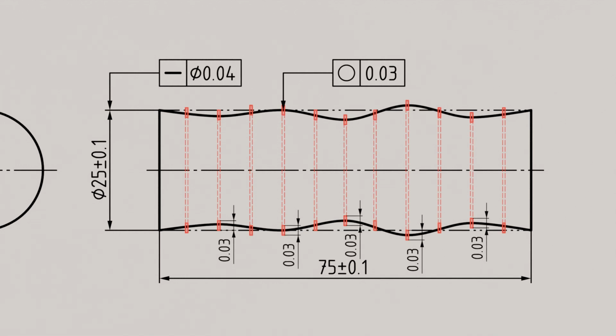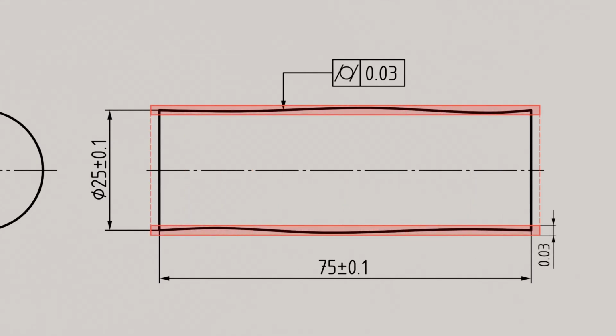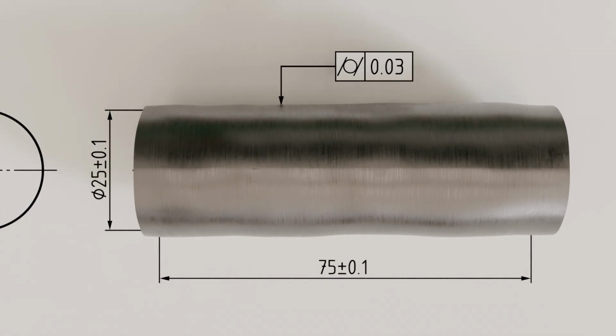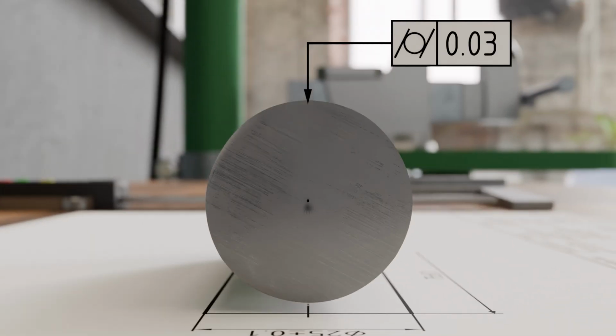For cylindrical parts, the deviation from the cylindrical form is limited by defining the tolerance zone not by two concentric circles, but by two coaxial cylinders, which together form a hollow cylinder. This sets the same inner and outer diameter as form tolerance limits for every cross-section. The actual geometry must lie within these two coaxial cylinders. The symbol for cylindricity in the feature control frame is represented by a circle bounded by two parallel lines. The tolerance value indicates the distance between the two tolerance cylinders.